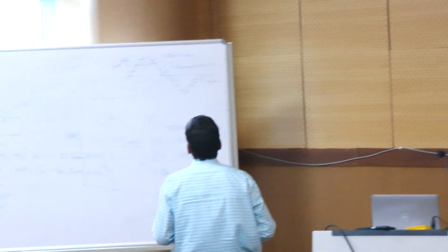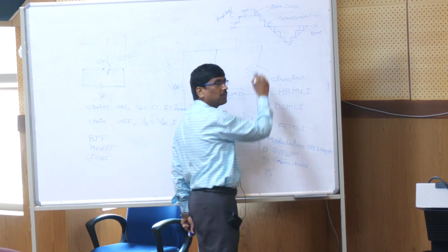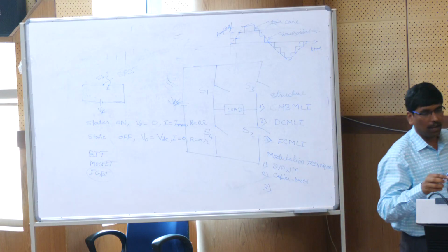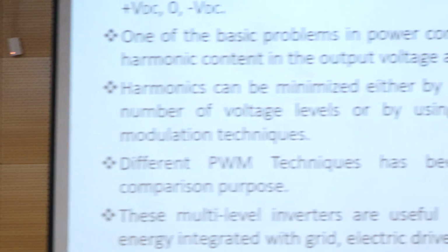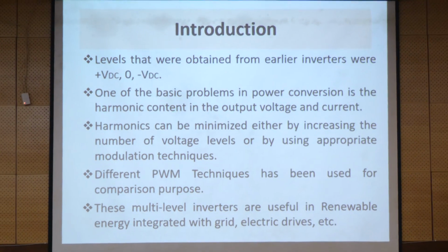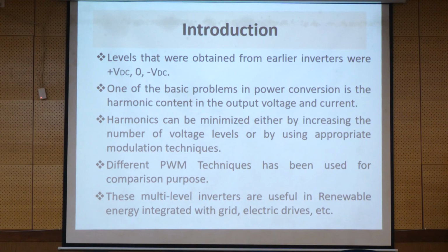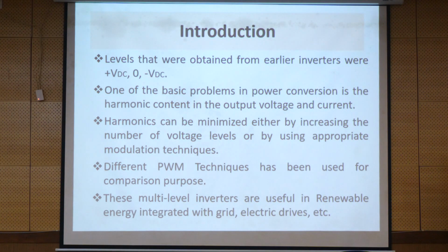This is what we want to achieve, the sinusoidal waveform. You know that for power quality, if it is of good quality, it should give a sinusoidal output. Even though we do accept an inverter with a square wave output also, the torque is going to be pulsating in nature and the machine performance is going to be lowered.